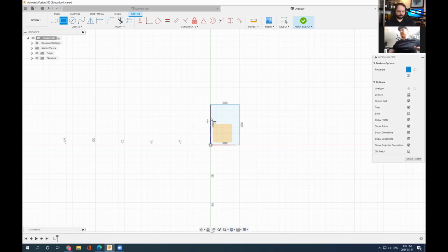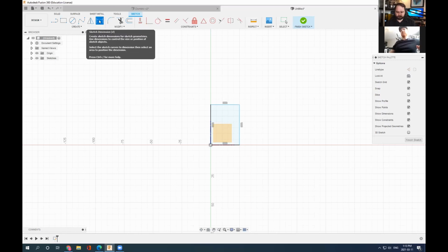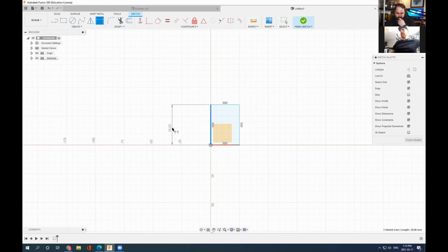So we have our shape, but it doesn't quite meet the domino sizing form factor that we discussed earlier. So that's okay. We're not stuck. We don't have to delete it. We can basically edit the features. Up in the top, there is again going to be this line with a blue line between them, and that's going to allow you to make dimensions for your object. So click on that, and then come back down to your sketch and choose the side line here and pull out. Once you've pulled out, you can click again to lock it into place. Now I can decide what that height is just by typing into this box.